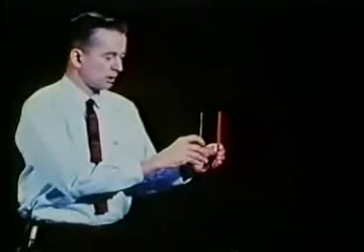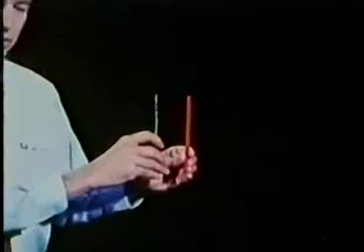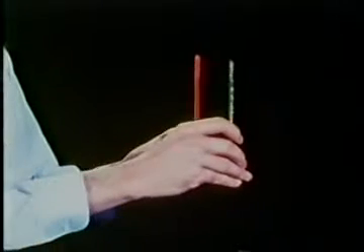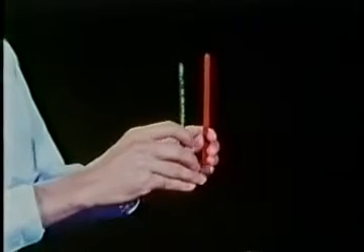The explanation lies in a theorem proved by Taylor and Proudman that depends on vorticity considerations. This theorem shows that for low Rossby number, low frequency ratio, homogeneous flows, the motion is nearly two-dimensional in planes perpendicular to the rotation axis. Fluid lines parallel to the rotation axis are also the vortex lines of the absolute motion and tend to remain parallel to that axis.